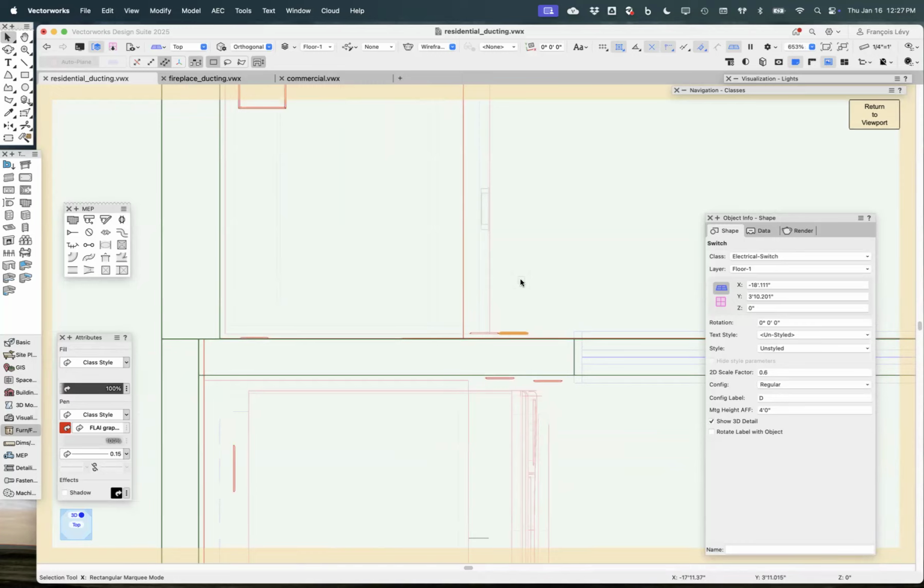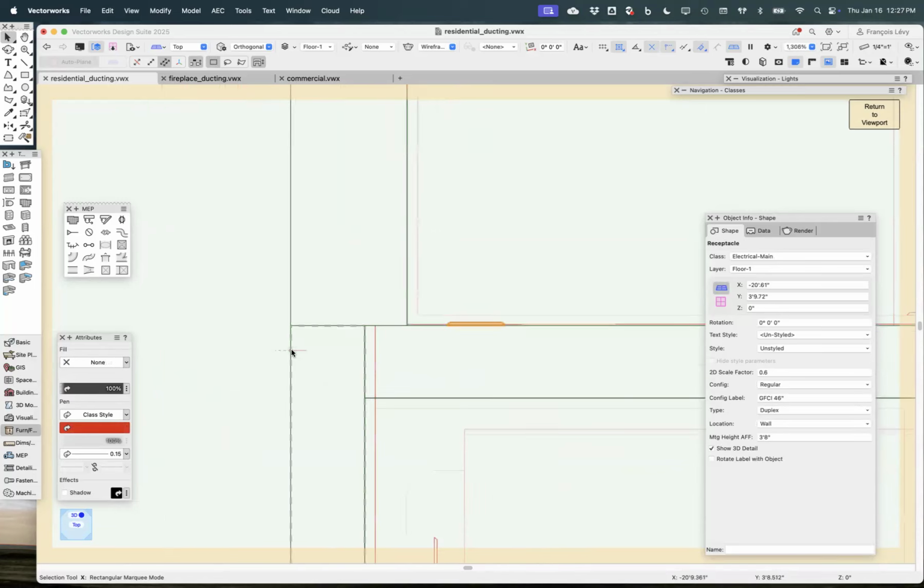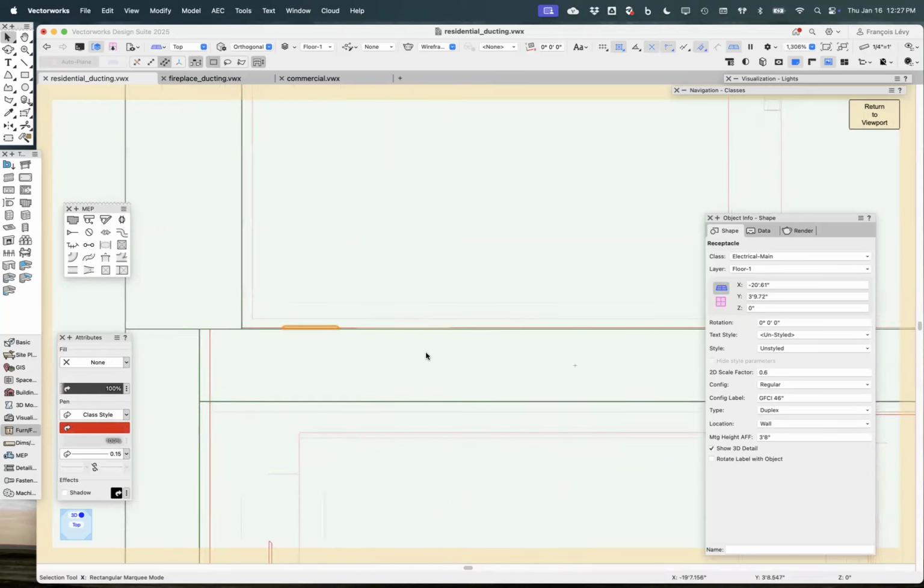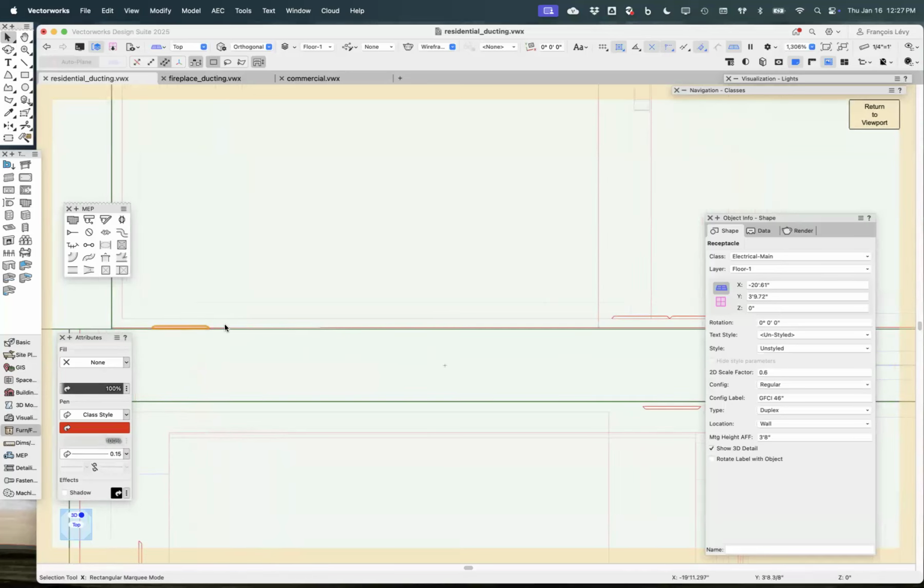But for design purposes and being able to visualize, okay, where are these things, right? And you want to be careful too. Here's something I'm just going to tell on myself. Here's one that was not properly placed. You can see a very faint line here that I'm hovering over. That's the gypboard. And this one was placed on the frame wall rather than on the gypboard. So that's a good argument for inserting these in the wall, which I don't typically do, right?